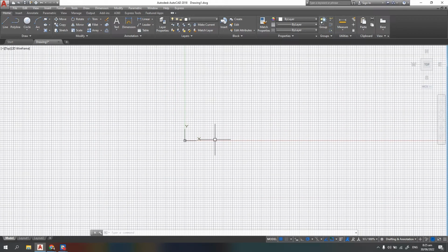Once you move your origin, if while you are dragging it you move it to the center, that means you reached the origin. If you move it and the origin doesn't move, like earlier when we moved several times, and you can see that the origin is still in the lower left corner of your drawing area, that means you have not yet reached 0,0.